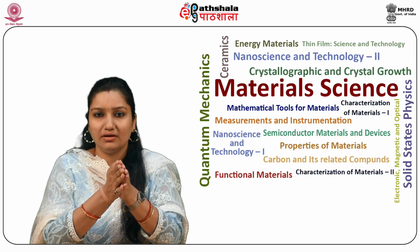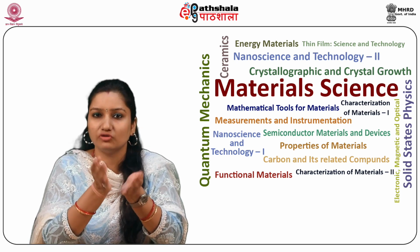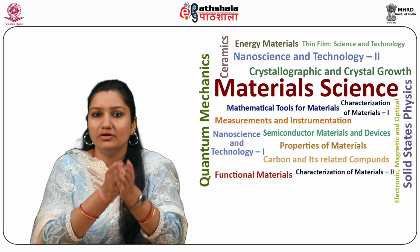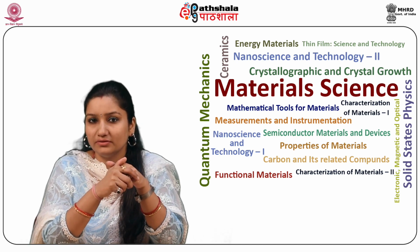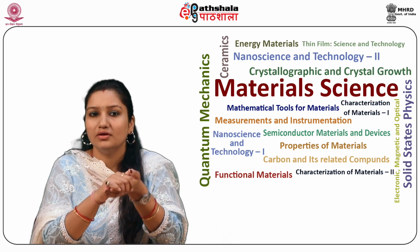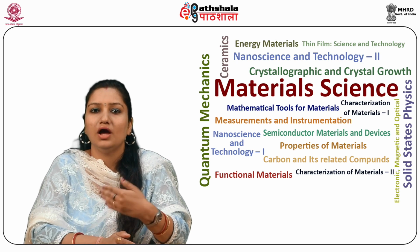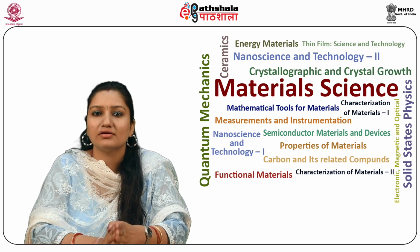The next technique for the vacuum deposition of thin films is molecular beam epitaxy, or the MBE technique. MBE is a technique to deposit monocrystalline film. Epitaxy means the growth of crystalline layers on a crystalline substrate. So MBE involves epitaxial growth where the interaction of one or more molecular or atomic beams occurs on the surface of a heated crystalline substrate.